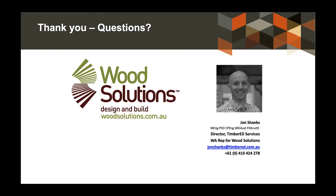I've got a question from one of the participants. What's your opinion on timber concrete composite floors, especially in high seismic regions where the diaphragm forces are very high? Yeah, look, timber concrete composites are really, really interesting, and I'd say at this stage, it's a specialist market. It started historically by people using concrete screeds to upgrade existing floors in things like houses that they were converting into offices in European town centres and so on. Works really, really well.